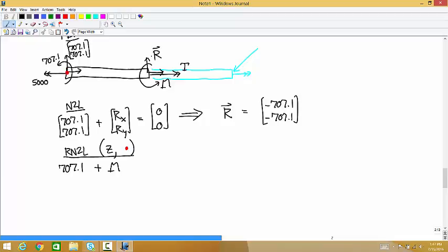So what's the moment arm for that y component of the force R? 0.5. Yep, so we have a moment arm of 0.5 times the force Ry, the y component of that force R. And then if you think of that force Ry causing a rotation around that red dot, would that force make it go clockwise or counterclockwise?